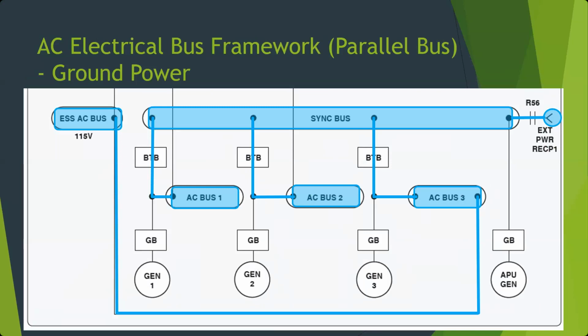It serves as a contactor and a circuit breaker, so it can be turned on and off, but also if there's an overcurrent, it will trip. If there's an overcurrent on AC bus 2, hopefully this will trip so that it doesn't overcurrent the rest of the system. This is that fault tolerant design. This is the older version of it, but bus tie breaker. Okay. And then you can see our AC essential bus gets power from bus 3 over there.